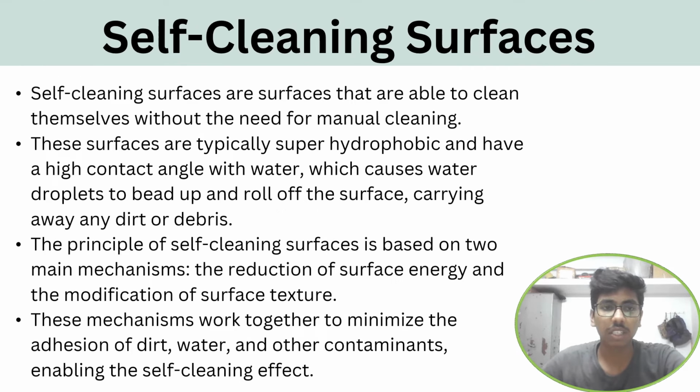Self-cleaning surfaces. Self-cleaning surfaces are surfaces that are able to clean themselves without the need for manual cleaning. These surfaces are typically superhydrophobic and have a high contact angle with water, which causes water droplets to bead up and roll off the surface, carrying away dirt and debris. The principle of self-cleaning surfaces is based on two main mechanisms: the reduction of surface energy and modification of surface texture. These mechanisms work together to minimize the adhesion of dirt, water, and other contaminants, enabling the self-cleaning effect.